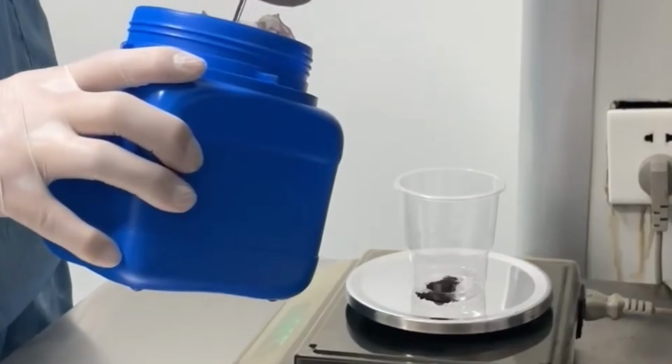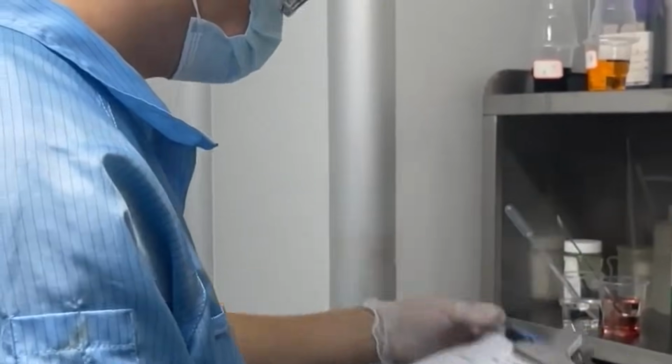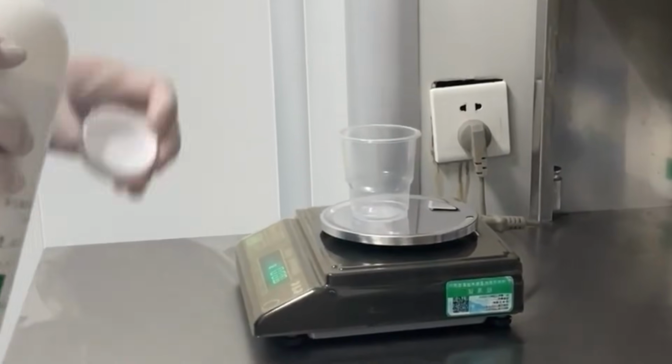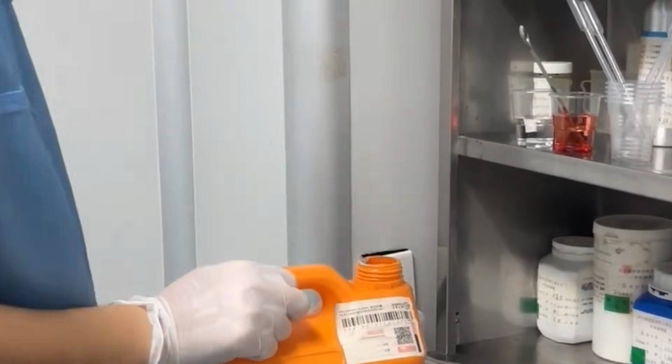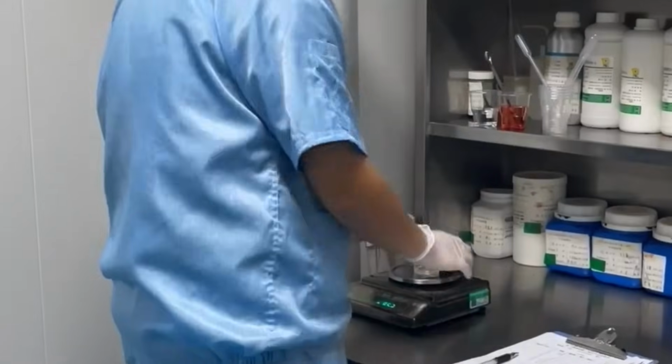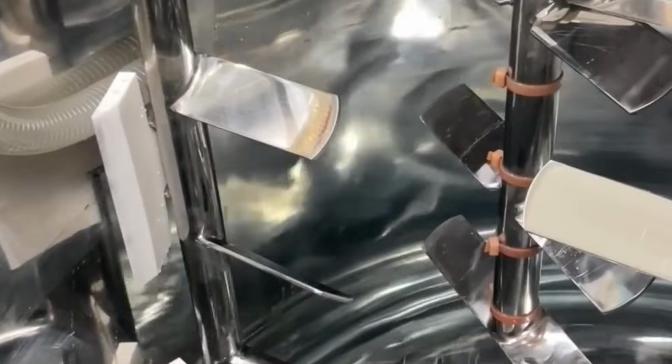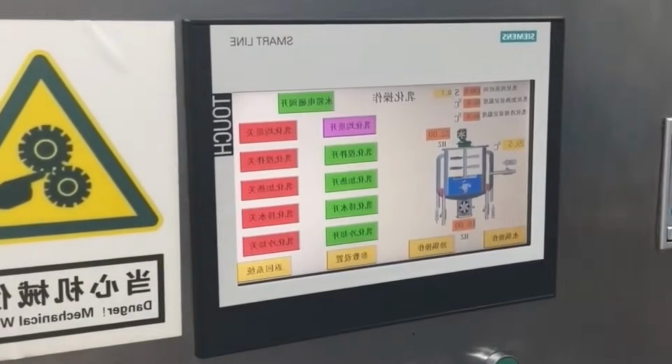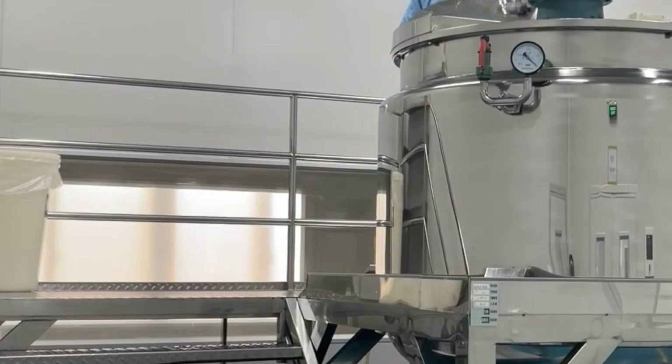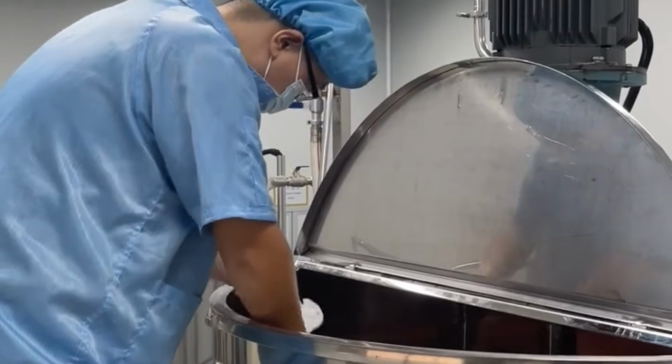Batch production starts with loading water into a stainless steel jacketed mixing vessel fitted with high shear agitators. The vessel is mounted on load cells to allow for precise weight-based dosing of each component. All ingredients are added in a controlled sequence based on formulation parameters pre-programmed into the batch control system.